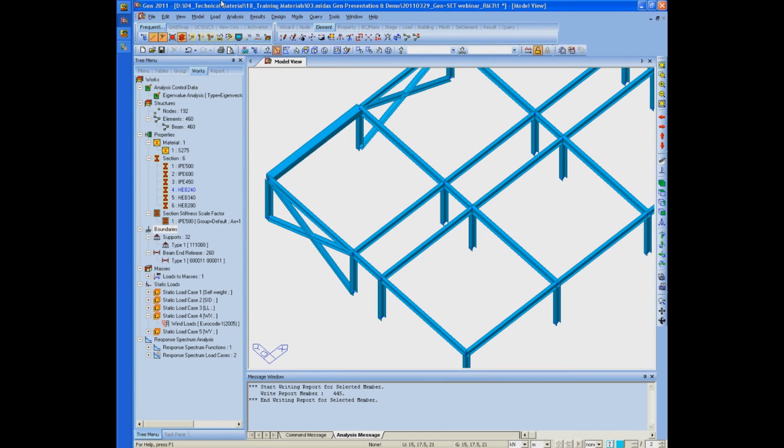For the masonry structure, we provide only analysis, as it performs the plastic analysis. For design, we provide only the RC wall design, not the masonry wall design. If we want to check the capability of the masonry wall, then you can perform the pushover analysis. So for the masonry type, we provide the plastic analysis or pushover analysis, and for wall design, we provide only the RC wall design.